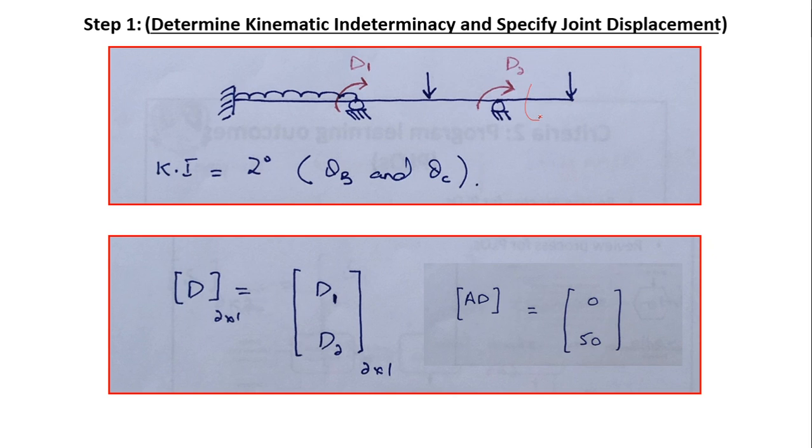As a result, the resistive moment would be anti-clockwise, because the load is making a clockwise moment. So the resistive moment would be counterclockwise like this. And if I have to balance this, I have to apply it like this on this support. So this moment would be my applied moment.